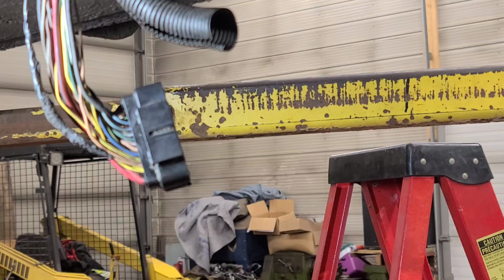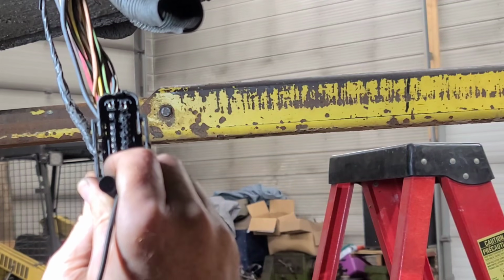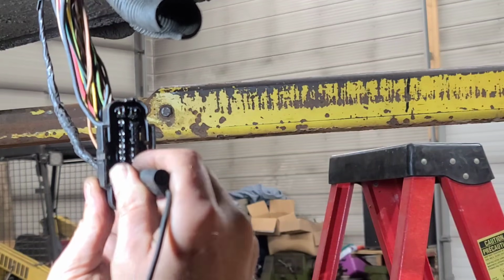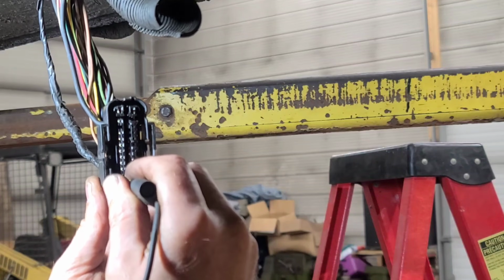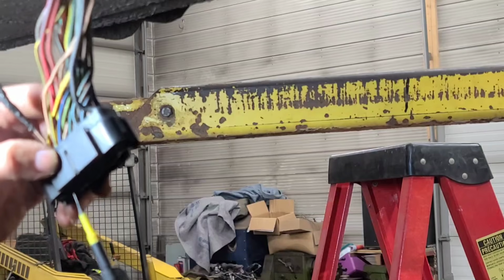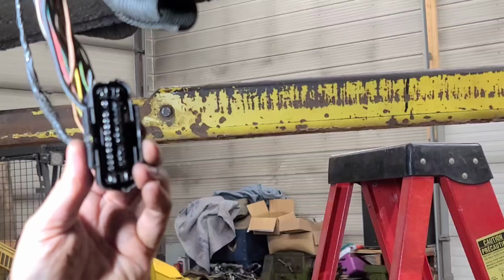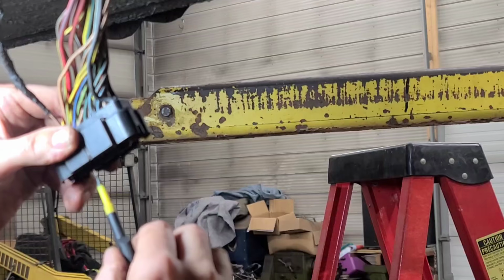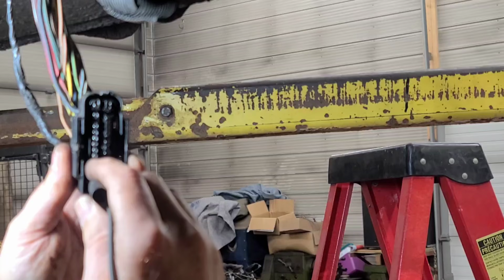Pin grip is crap on these things. You gotta be careful when you're probing these pins with probes of nothing more than 24 thousandths of an inch. But pin grip on this pin is non-existent. That one has got some grip. That one's good, but these pins are spread apart, so if you're probing these pins with a probe, you got to be careful. Like this one here, you can see that there's good pin drag there. But this is a CAN bus pin here, and there's no pin drag whatsoever.